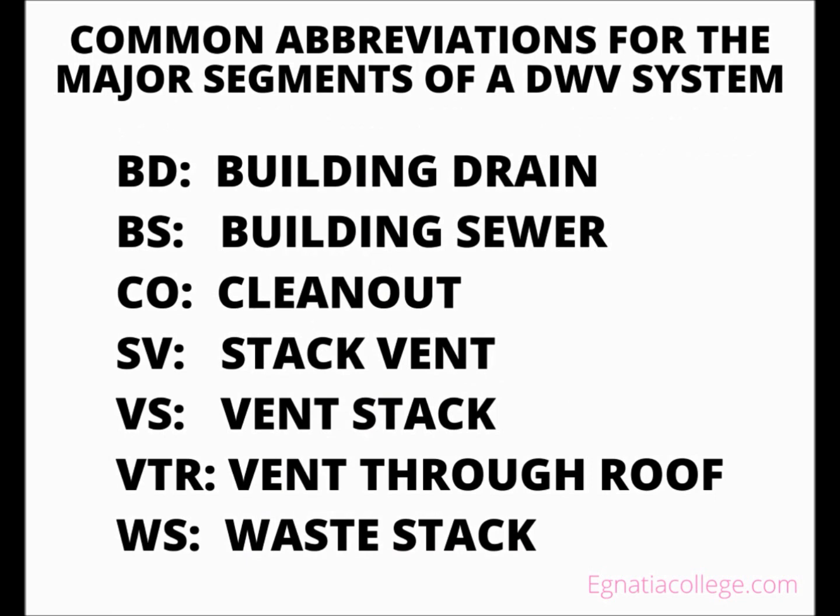The common abbreviations for the major segments of a DWV system are BD, building drain; BS, building sewer; CO, cleanout; SV, stack vent; VS, vent stack; VTR, vent through roof; WS, waste stack.